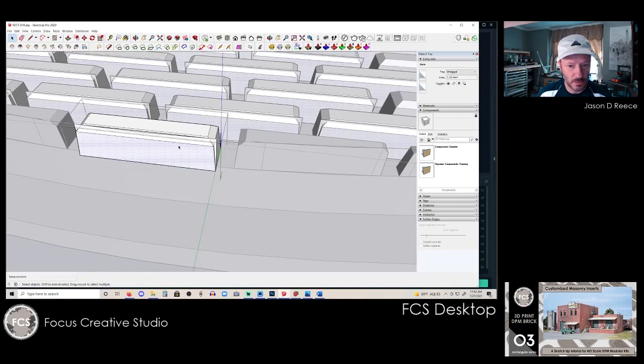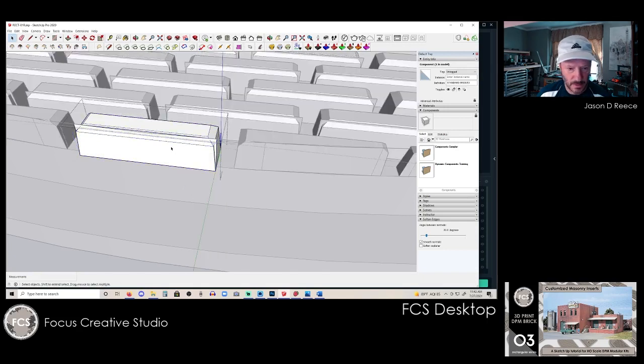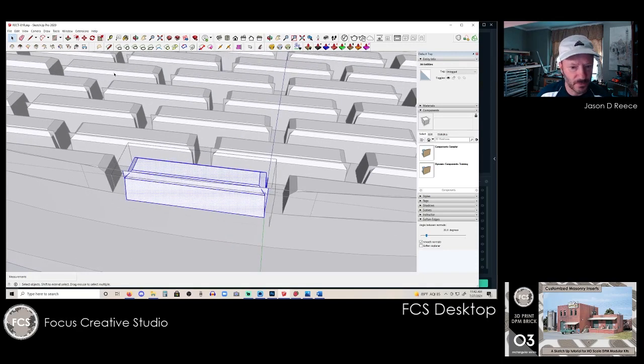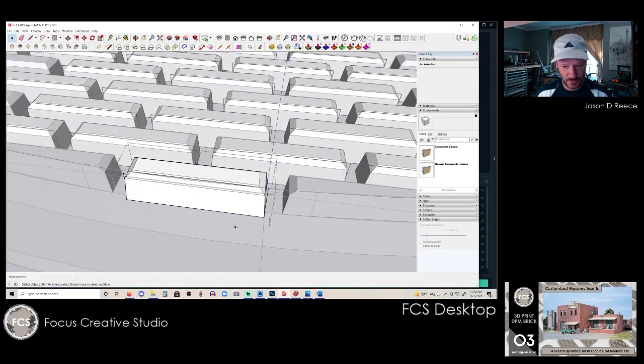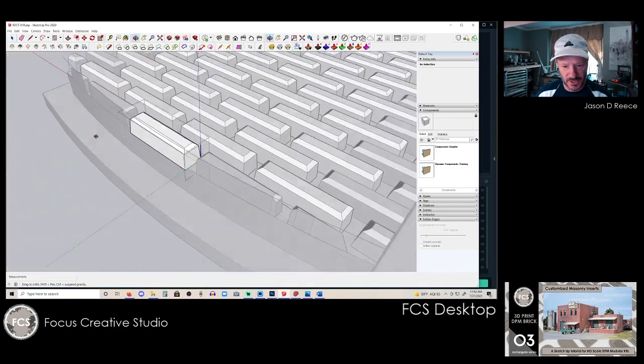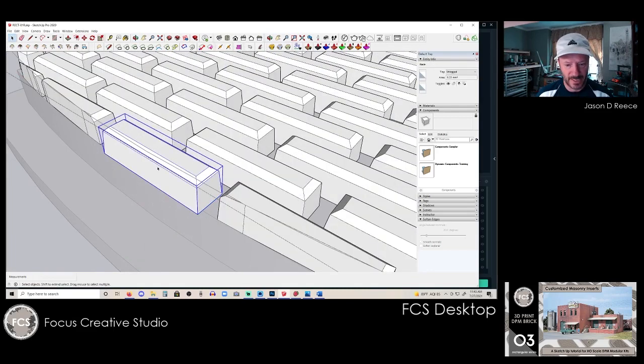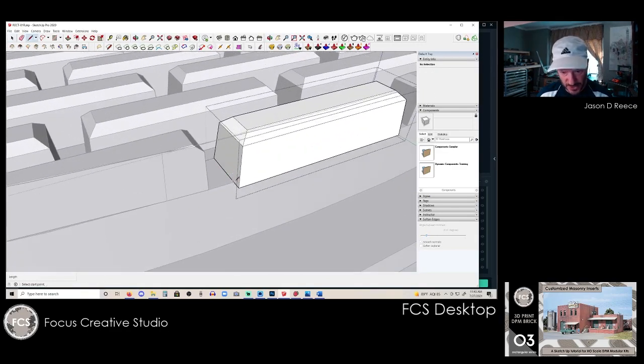And now, make this unique. Edit. Oh, I messed this up. My bad, my bad. Okay, so we want to undo what we just done. We need to make this unique first. Otherwise, it copies that into all my other components. So, good thing to be mindful of. I didn't catch it as we were going. So make unique. Now jump in, do what we just did.